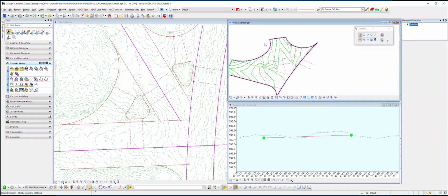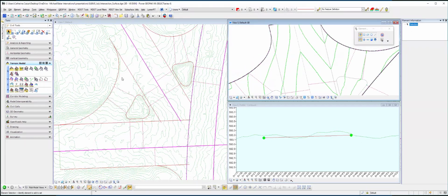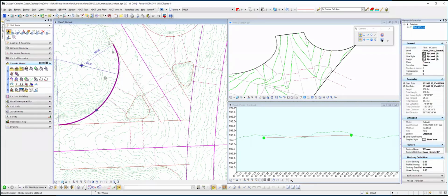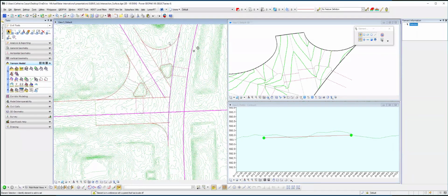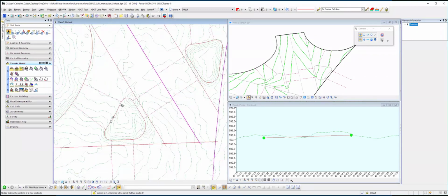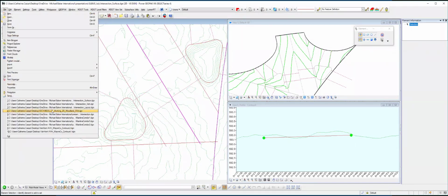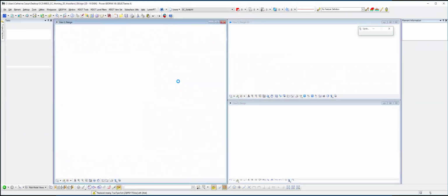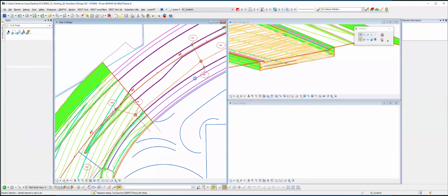So from there, once you have your pavement depth, you can add a bunch of bells and whistles, which I didn't do for this particular intersection. It takes a little time, but from here you can easily add linear templates or corridor models all the way around in order to get a more refined looking model and get your islands constructed. I never do the sidewalk ramps as part of my model. And I'm going to go ahead and show you a completed model from a different project that I just finished up earlier this year that actually has with it all the bells and whistles and everything done.